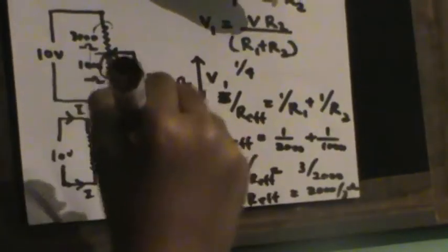So the total effective resistance will be R effective T. So we found the effective resistance between these two resistors. This is actually a single resistor, but we divided according to the potential divider. That is the importance of potential divider. We divided this resistor into two parts using this slider. Actually, we didn't physically divide, we imaginarily divided